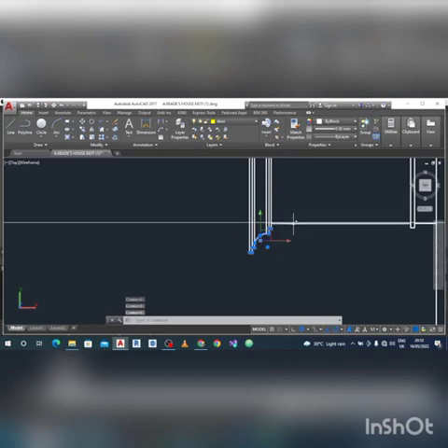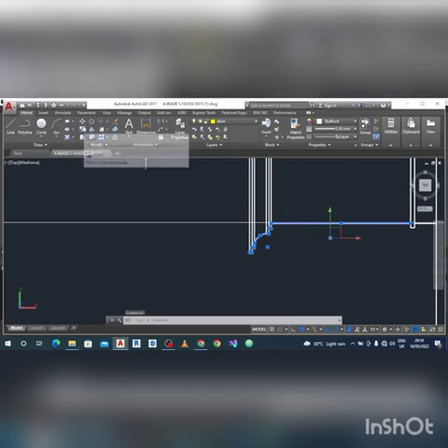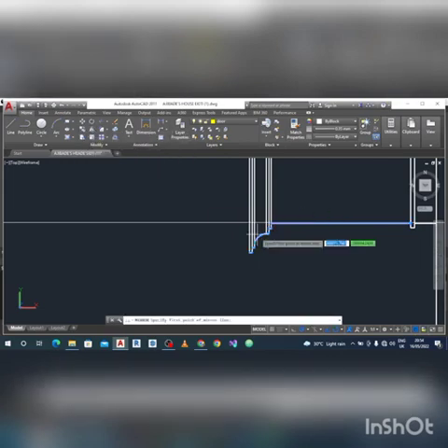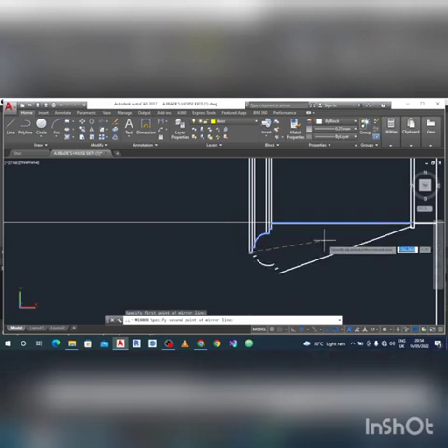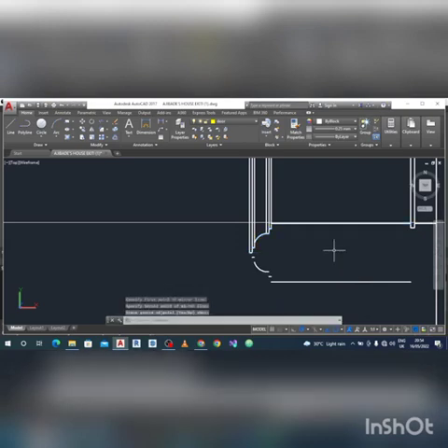So picking all our parapet design, then we'll pick on this as well. What are we doing? We want to mirror it. Click on mirror. Let me use this point as my reference point, then I'll mirror it like this. Yep, then enter. Once I'm done, this is a double line, so I'll click on one of this and on this as well, and I'll highlight, making sure I highlight every other thing.